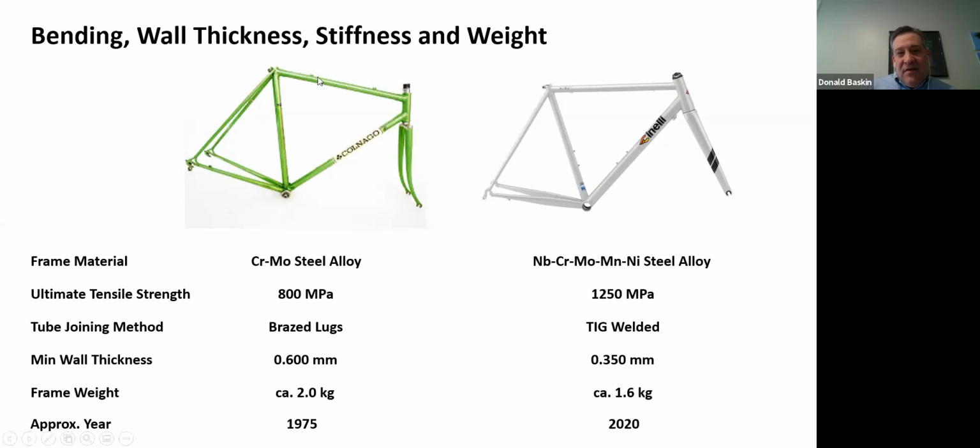Okay, so these tubes are smaller and thicker walled. These tubes are bigger in diameter and thinner walled. This is actually a lot stiffer and weighs less than this one. So that's the structural efficiency science in action, let's call it, okay?